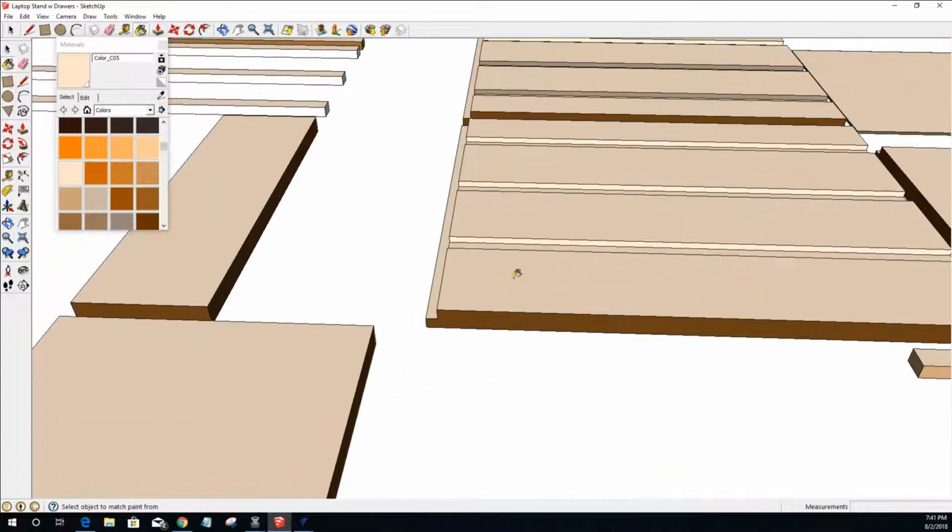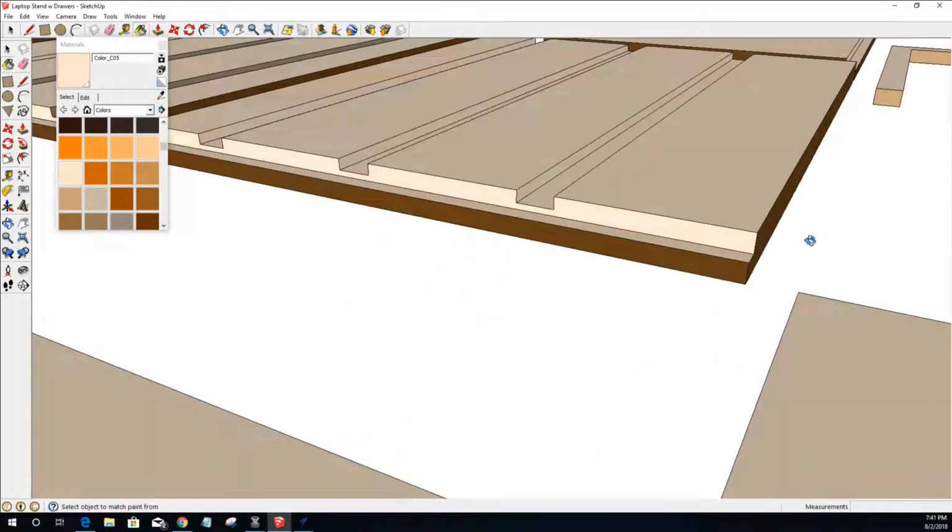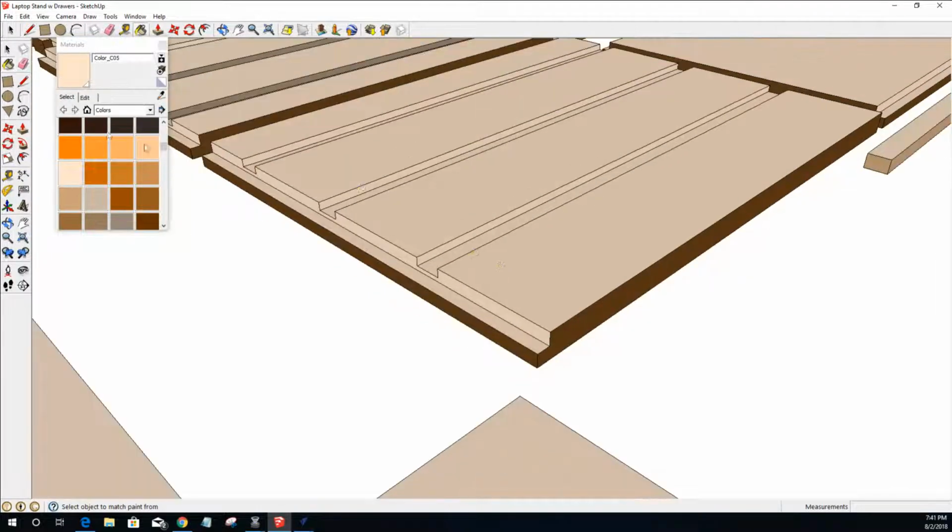And so if we look here at the cabinet side, we've got these 3 grooves running along the part, and we also have this rabbet that's cut a little lower. The grooves are cut about 1/4 of an inch deep, and then the rabbet is cut 3/8 of an inch deep along one end of it and everything.